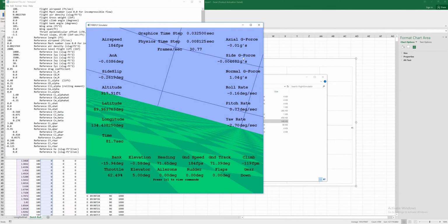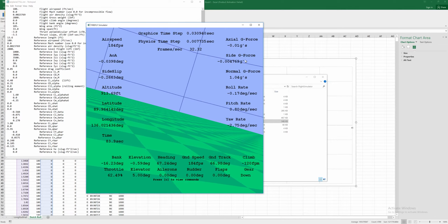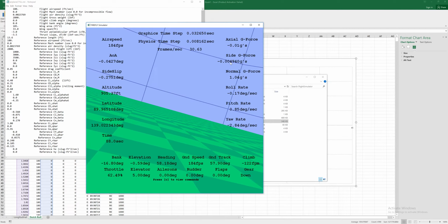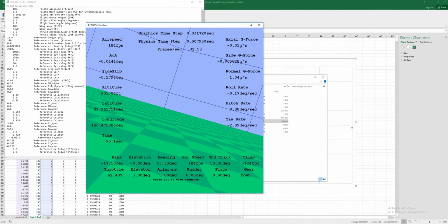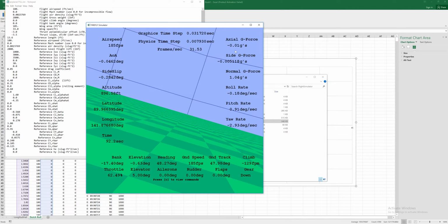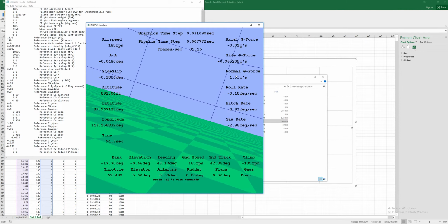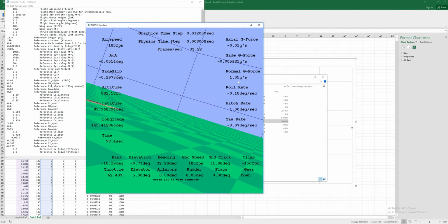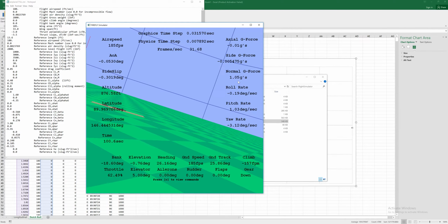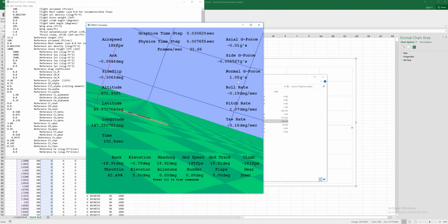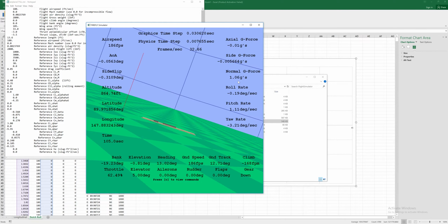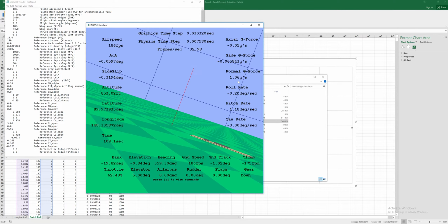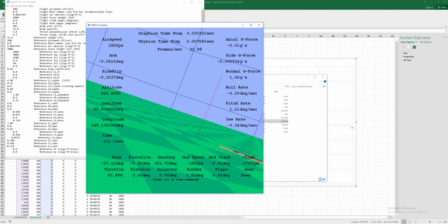There's a small side force on the aircraft, or on the pilot, so he's feeling a very, very small side force, but not something that was really noticeable, most likely. So really it's this normal force. He really can't tell that anything's going on. And so if he were in a cloud and didn't have instruments, he could now fly out of that cloud and be completely disoriented, not having felt at all that the aircraft was doing something odd.